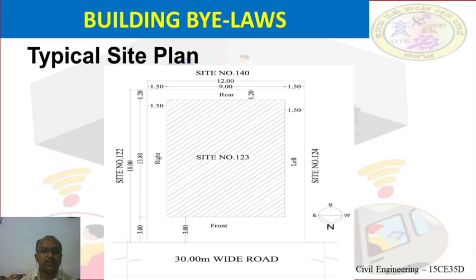Here the site number is given as 123, and for all the adjacent four sides of site number 123, that is the front, rear, left and right, the margins which are kept according to the local building bylaws are to be clearly shown, and the width of the road, whether it is a 30-meter road or 15-meter road, which is to be clearly indicated, and on which direction it is. The road is lying on the north side with a 30-meter width.